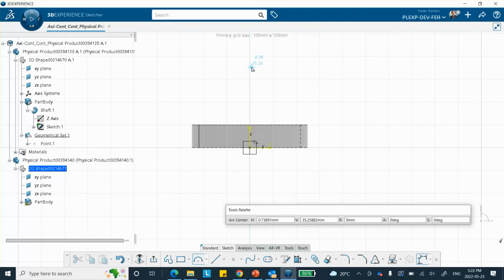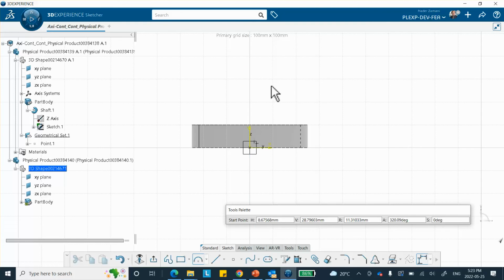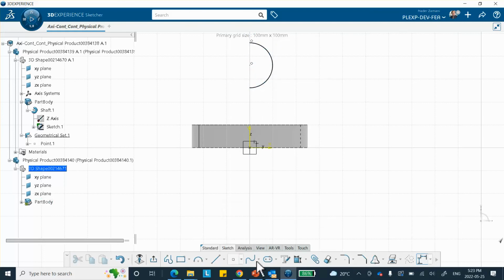Let's put the center here. Oh, try it again. Center here. We start on the top. And there's my arc. Okay. The radius of this was 5 millimeter. I want this thing to come down and sit on that workpiece. There are different ways of doing it, for example, you can do this point. You can do dimension between this point and this top line, and either make it 0 or right click coincident, it'll bring it down and put it there.